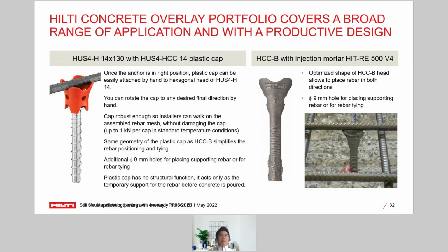I mean, the cap is very robust. It's good enough that the installer can walk on the assembled rebar mesh without damaging the cap. So this is one way you can, for example, carry out the concrete overlay installation by the mechanical screw. The other method, on the right hand side, is the chemical method using the epoxy,